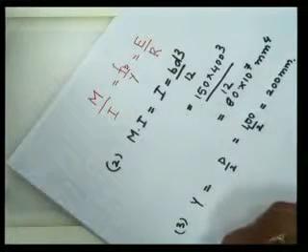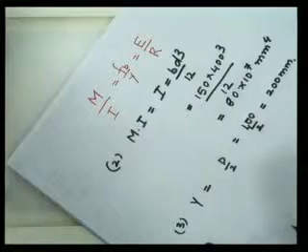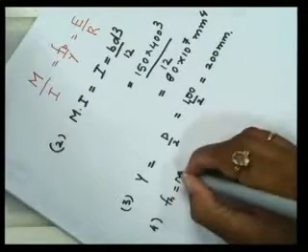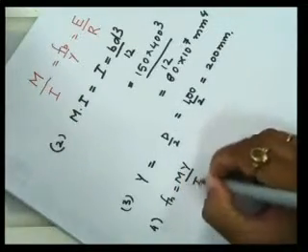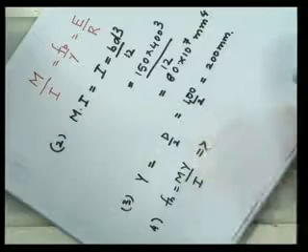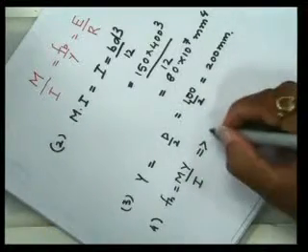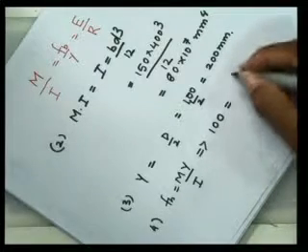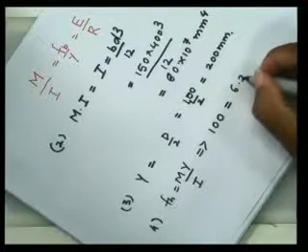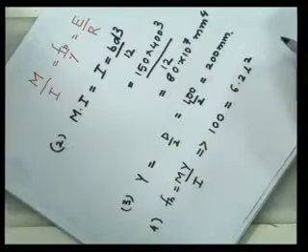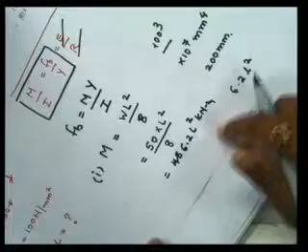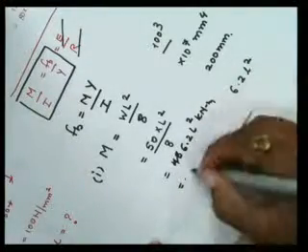So now we can substitute all the values in our standard equation. What is our standard equation? FB is equal to My upon I. What is the value of FB given? The value of FB is given as 100 Newton per mm square, equal to M, which we calculated as 6.2 L square. Now it is in kilonewton meters, so I have to convert it into Newton mm because everything is in Newton mm.